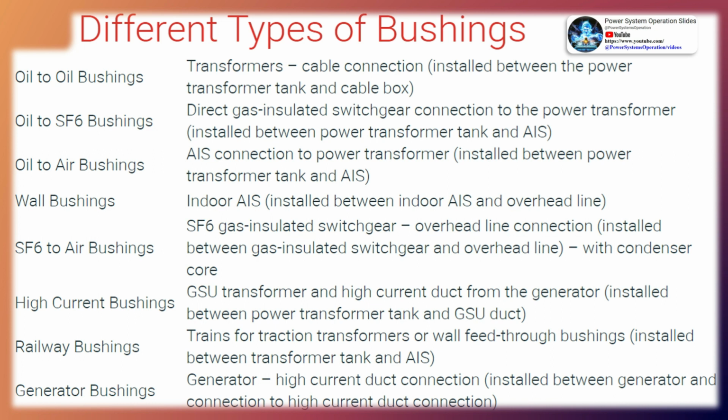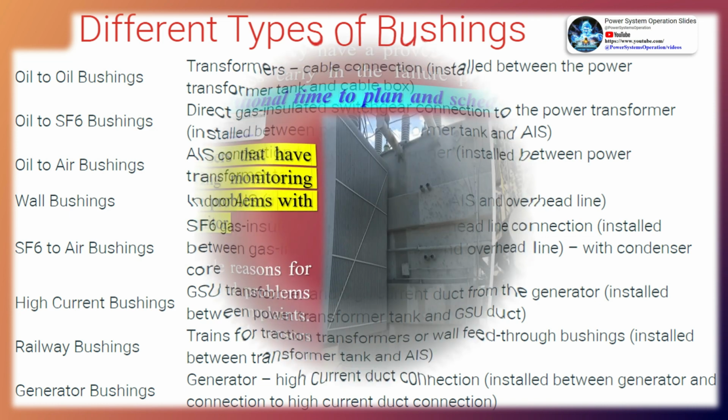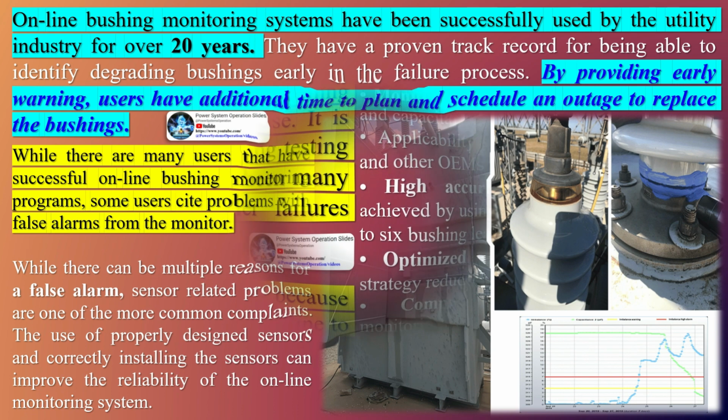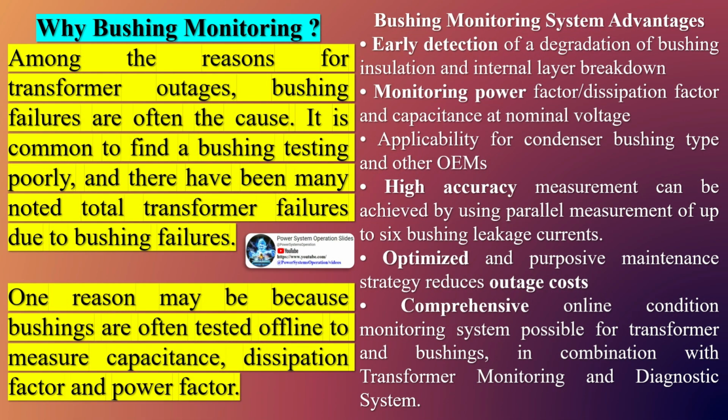In extreme cases, a dielectric failure in a bushing can result in total destruction of the high-voltage equipment in power transformers. For instance, losses stemming from an event of this type can be worth a few hundred times the unit cost of the bushing that originally caused the problem. Among the different existing types of bushings, the condenser bushing stands out in high and extra high voltage applications. In these bushings, the insulating body is made up of a staggered arrangement of several concentric cylindrical layers of insulating material and layers of conducting materials for the purpose of making the electric field as uniform as possible.